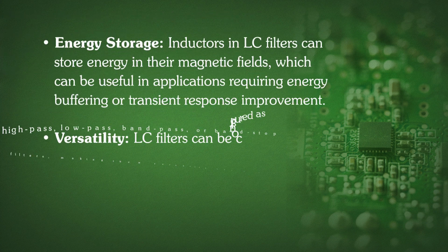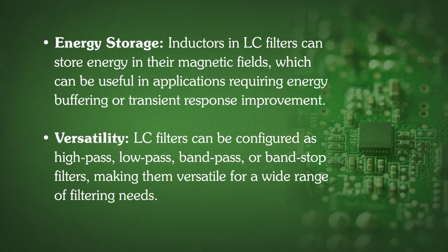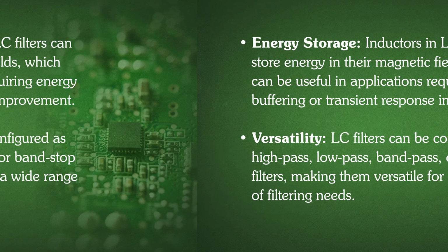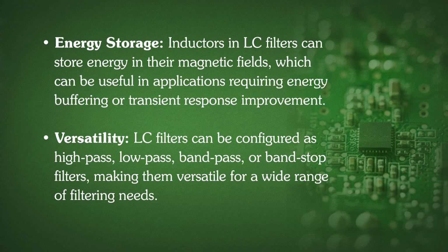Inductors in LC filters can store energy in their magnetic fields, which can be useful in applications requiring energy buffering or transient response improvement. Next advantage is versatility. LC filters can be configured as high pass, low pass, band pass or band stop filters, making them versatile for a wide range of filtering needs.